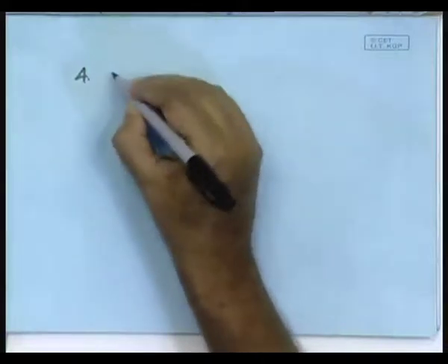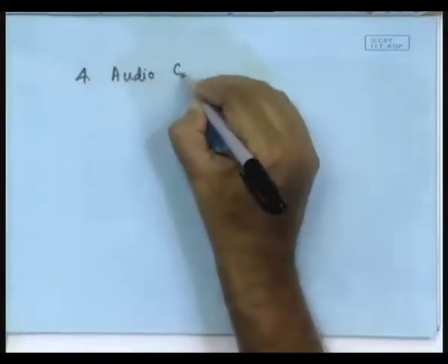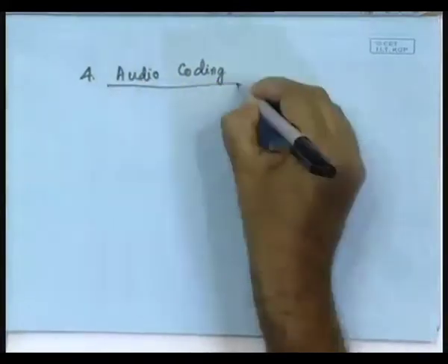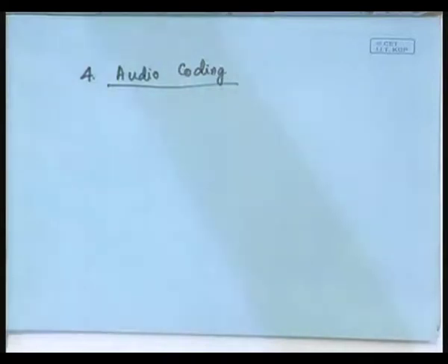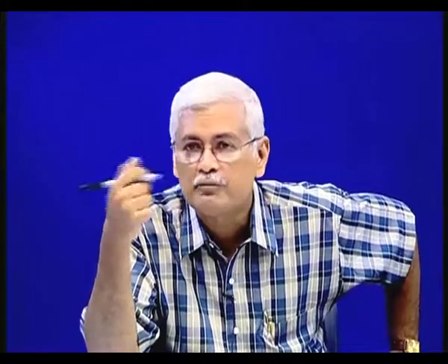also come to the question of how to efficiently encode audio. Now, again we are making a distinction between speech and audio. Speech is a simple voice quality signal which is restricted to 3.4 kilohertz. Now, if you get a channel of bandwidth which can just accommodate the speech samples, obviously the same bandwidth will not be able to cater for any high quality audio, say music, say some high fidelity musical instrument is going on, and then we will not be able to use the channel.